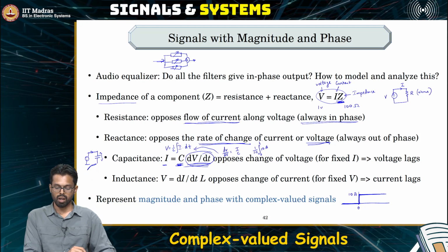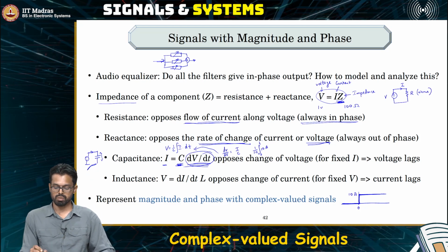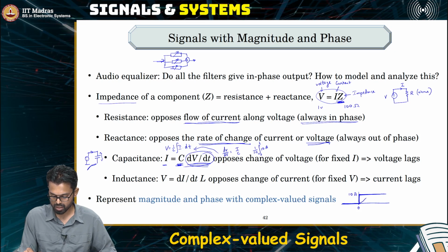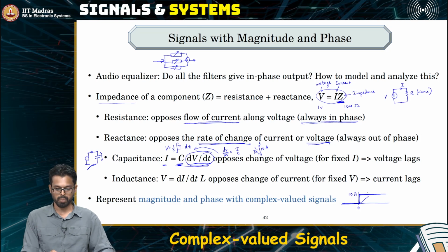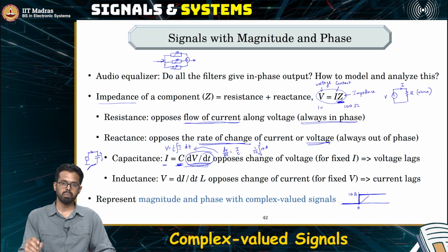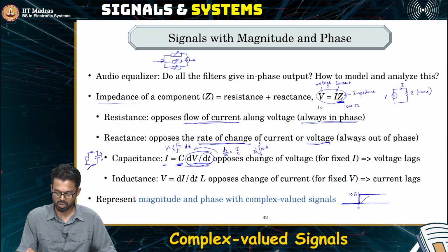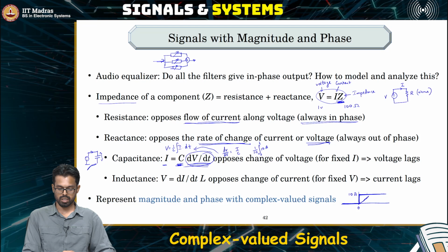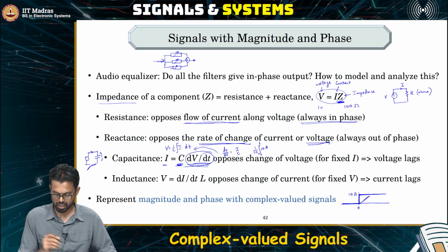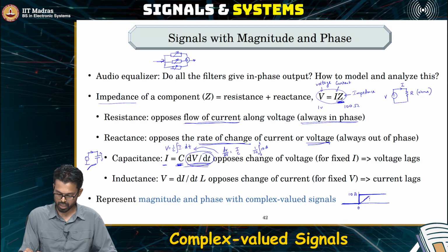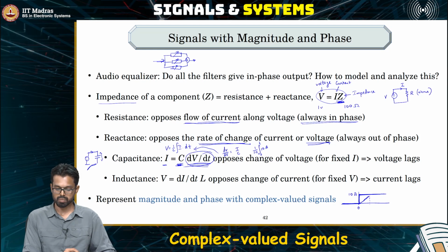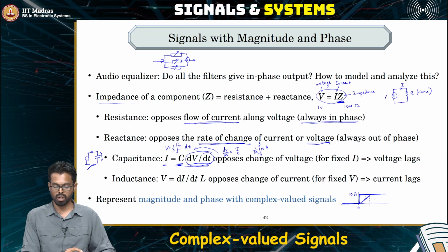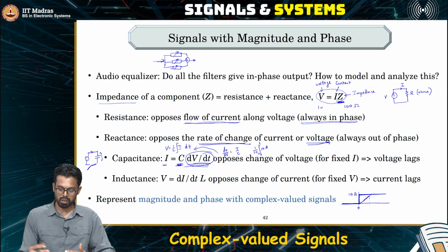One thing to note here is you have to just integrate this. If you are integrating it, it means that it will start at 0 and then it will start rising up slowly. Which means even though you are applying 10 amperes immediately, the voltage does not respond immediately. The voltage is slowly going to rise and then catch up with the current later. It will take so much time to catch up with the current, and then only reach this value of the current. Which means the voltage is going to lag behind.